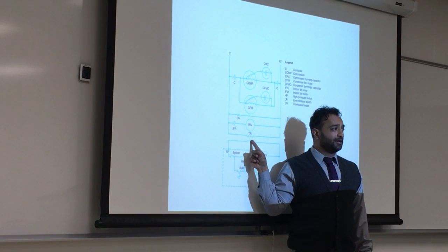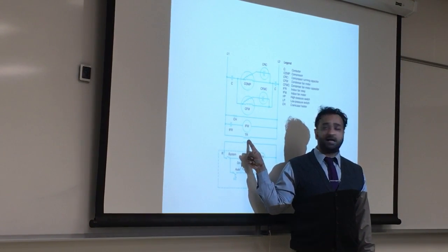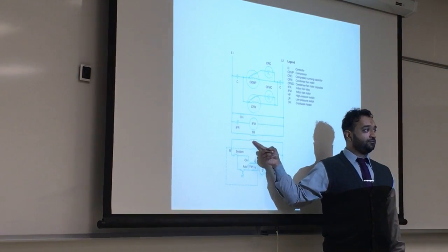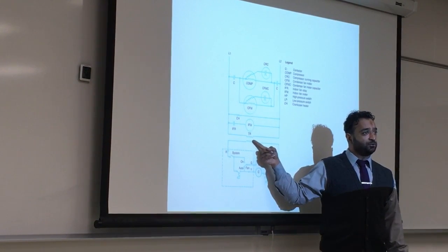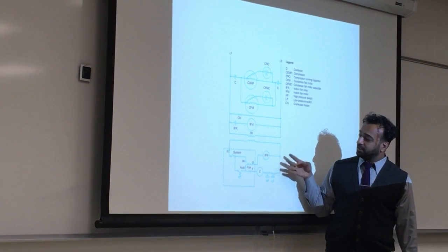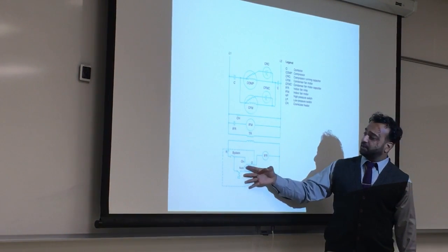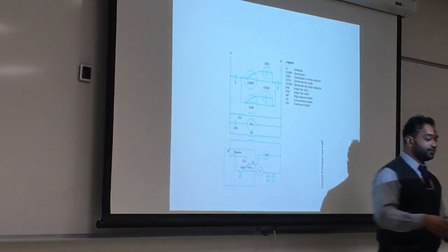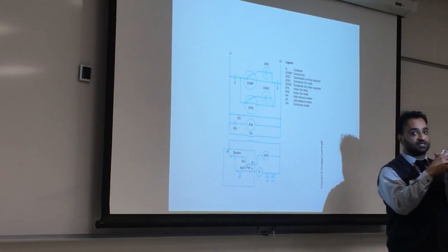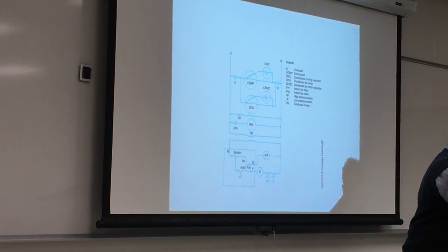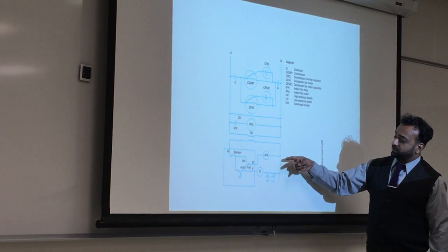What does this look like? Transformer. Excellent. Why do we need a transformer? For control. Control needs to step down to 24 volts. We go down. Here's my control. This is the loads. These are my controls getting circuit from the board. This is a similar thing. We have a transformer here to get our secondary circuit.